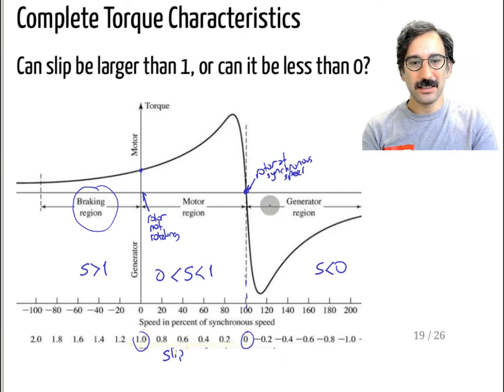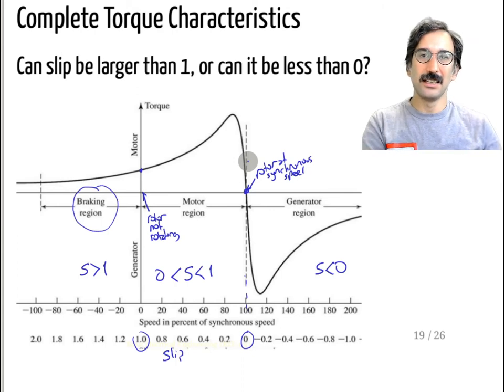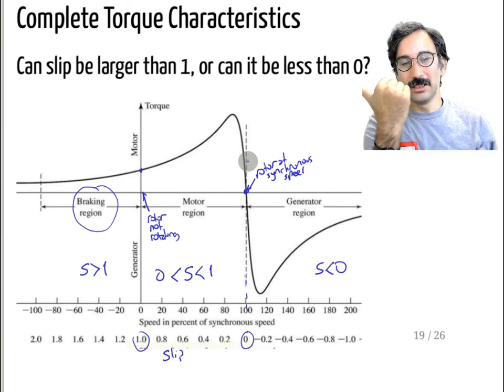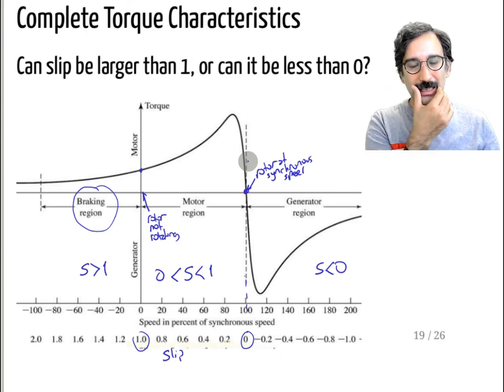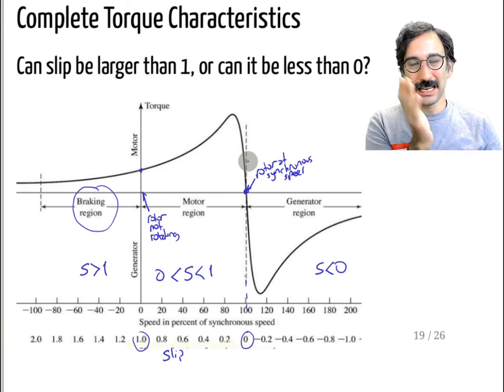For example, if your synchronous speed is 1500 rpm, then your rotor now starts rotating at 1600 rpm, faster than the synchronous speed. So now the rotor current sees a slower AC signal. Again, I don't want to get into real magnetics equations, but our equivalent circuit can still model those things. We will solve a couple of examples.